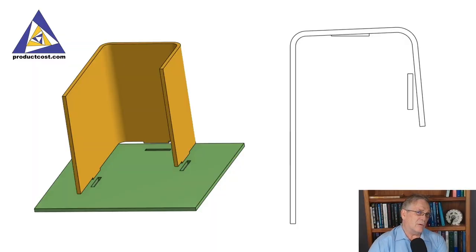This works because laser cutting is very accurate and very fast as well. It doesn't take much additional time to add the slots and the tabs during the laser cutting process, and thus it's very advantageous to do that during the cutting process than trying to do it later. It takes much longer to assemble the components, weld the components, than it takes to actually cut those components, and it's somewhat automated when it comes to the laser cutting process.